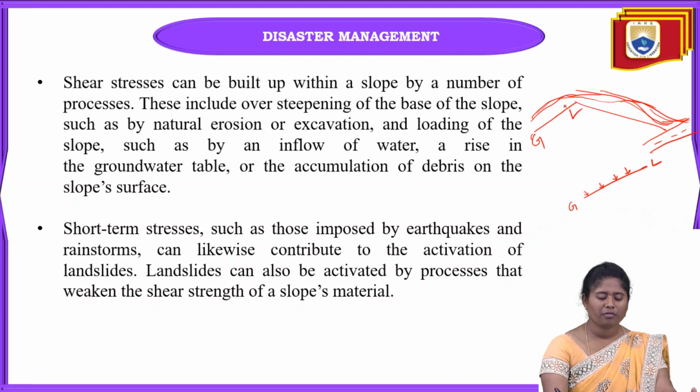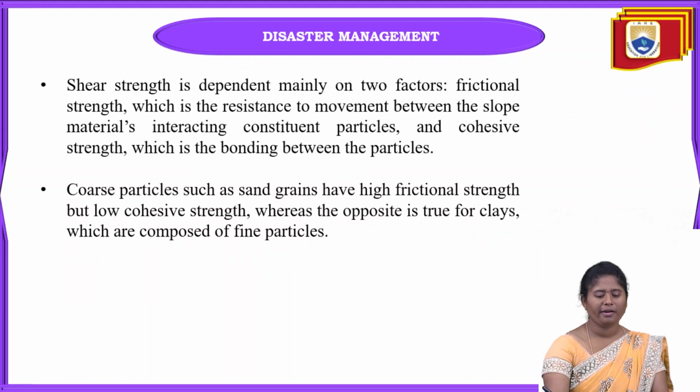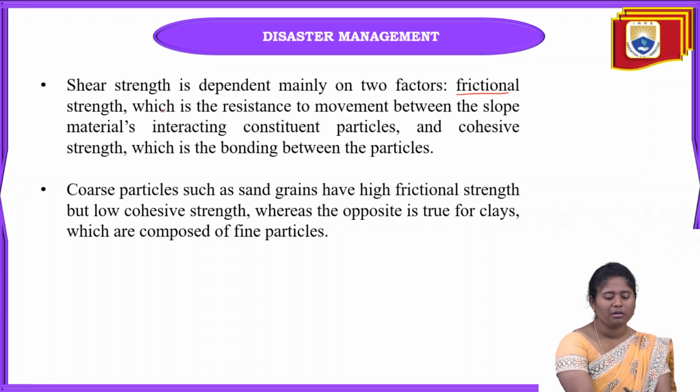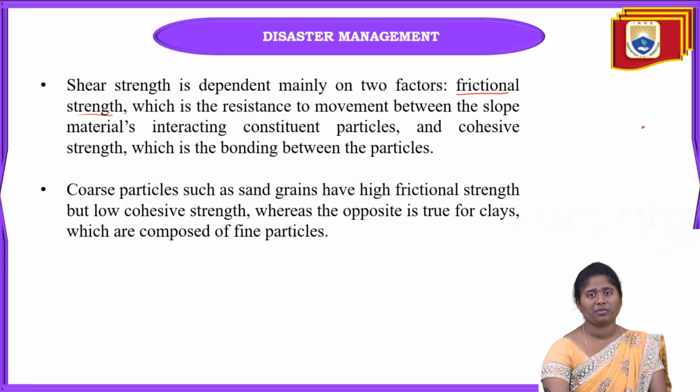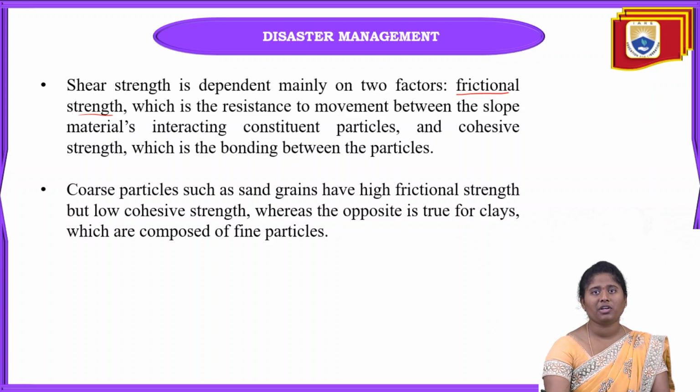Short-term stresses, as I already told you, such as rainstorms or earthquakes, occur in a fraction of seconds only. These are all short-term stresses, and by these stresses also there will be huge loss. Okay, and the shear strength mainly depends on two factors. The first one is frictional strength, which is the resistance to movement between slope materials, that is, the interaction of the constituent materials.